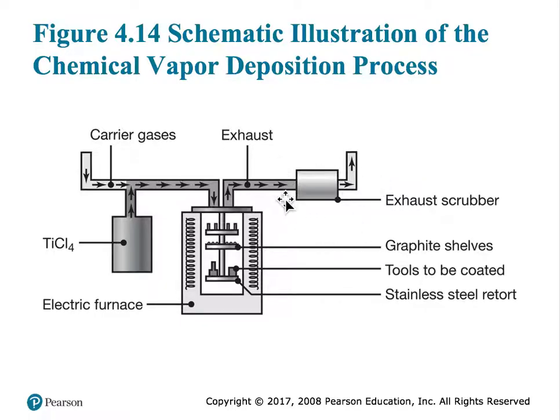So when that happens, that spray will react with the gases and form some kind of material. Say for example, if it is methyl trichlorosilane, methyl trichlorosilane will form particles of silicon carbide, which is one of the hardest materials known to us. And it will go and deposit in a very fine manner on top of the substrate material.